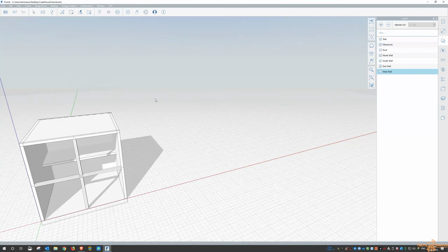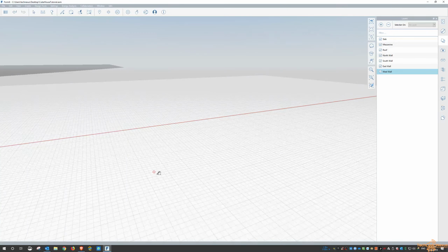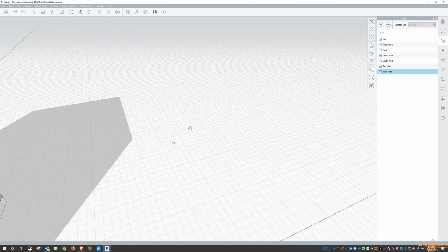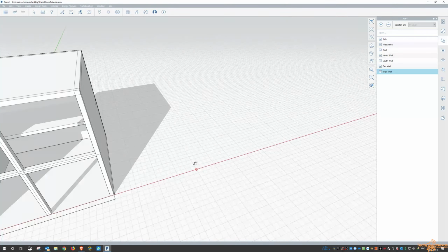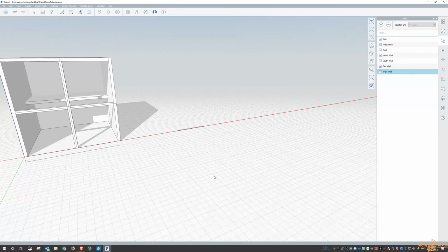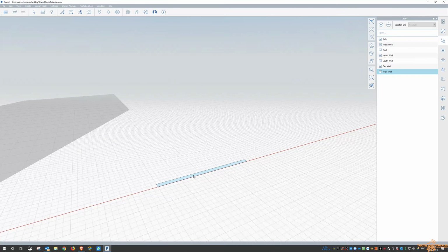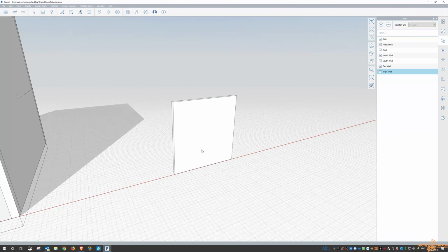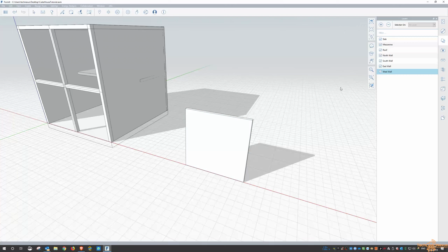Okay, so now I want to draw the glass. So I'm going to start out here somewhere, and then let's come out here and make it 200 mil thick, and then we know that we need to go 4.55. Okay, and then from that, zoom out, and then I want to extend that 4.7, and that's our glass.